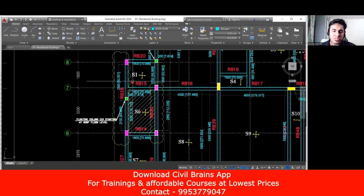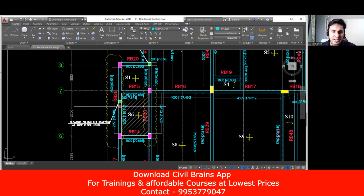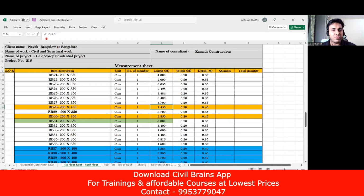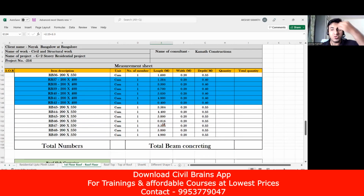Again, this entire thing is RB28. So I'll take the length from this column outer to this column outer, which is 2150. Again this column outer to this column outer, which is 2300. That is 2.3 plus 2.15. In the Excel sheet, you see I have done 2.15 plus 2.3, and I got 4.45. You're getting my point? In this way, you need to do it for all the beams, wherever it applies.